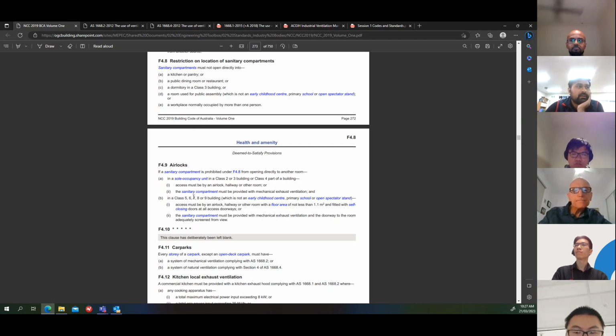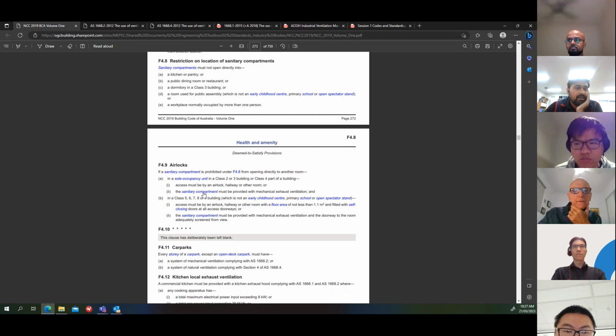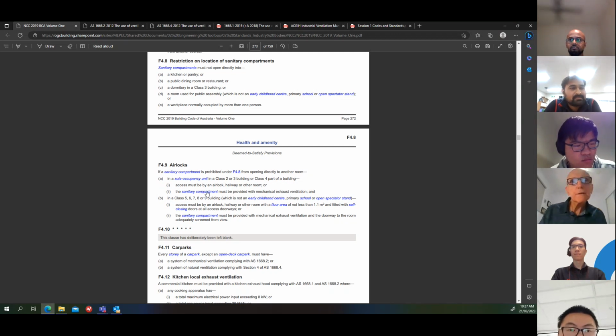Yeah, client's happy because looking at the capacity of that place, if we allow 200 people's fresh air, then heat load goes very high, so the cost goes up. So we want to keep the outside air down and use the windows. Yeah, I think it's a reasonable approach.